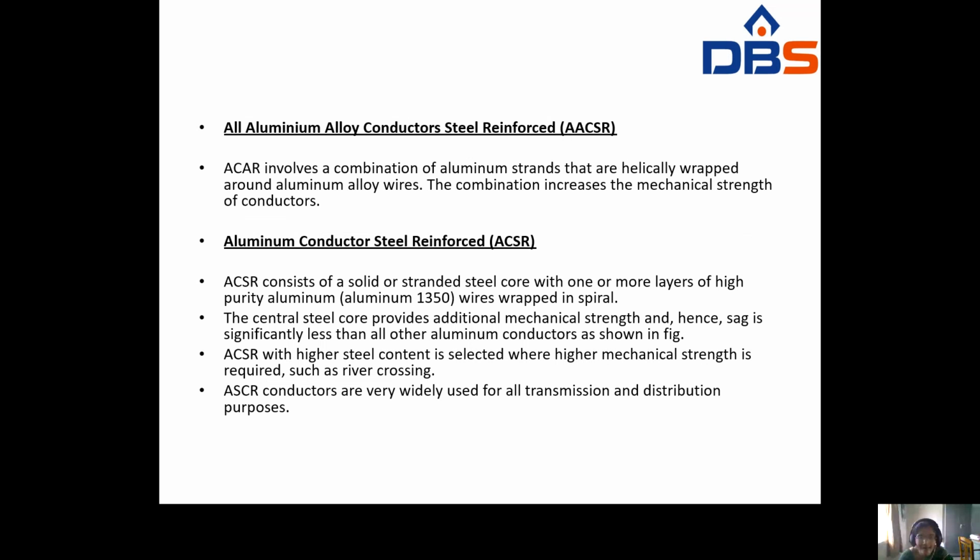So next is aluminum conductor alloy reinforced. Here is a combination of aluminum strands helically wrapped around aluminum alloy. The combination increases the mechanical strength of the conductor. So whenever you reinforce it, at that time it increases the mechanical strength of the conductor. So next one is aluminum conductor steel reinforced.